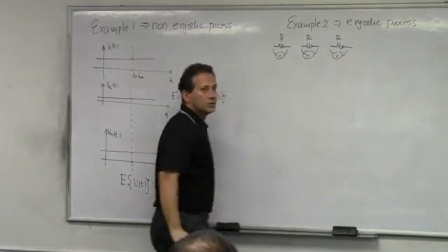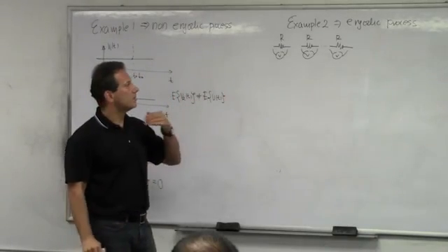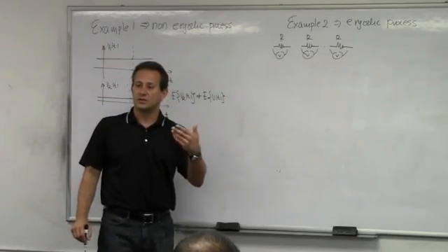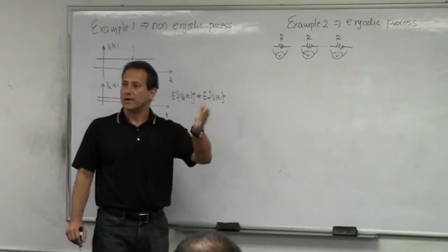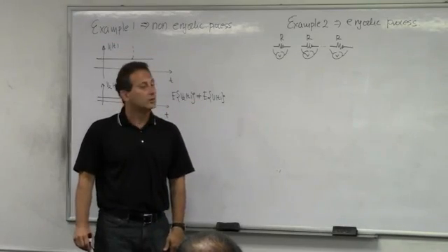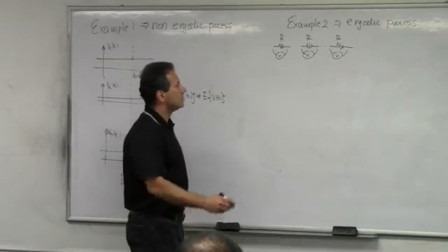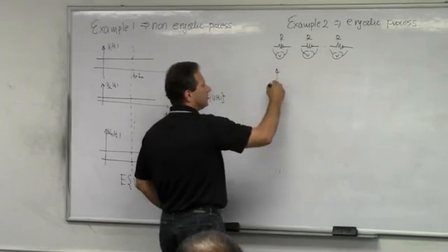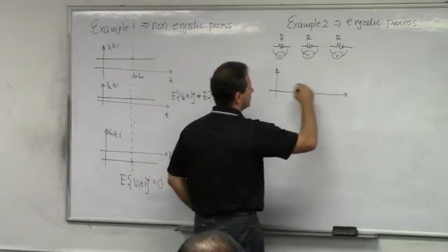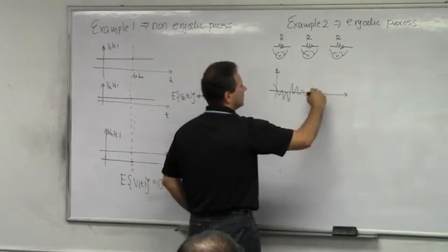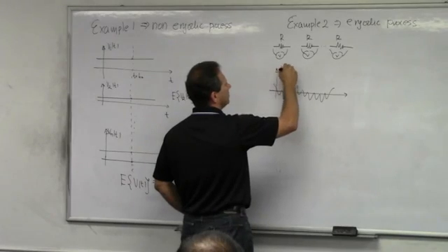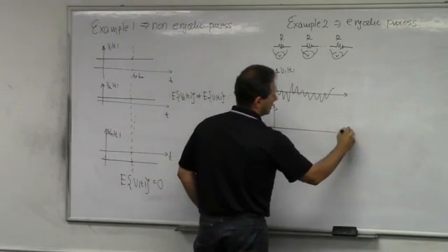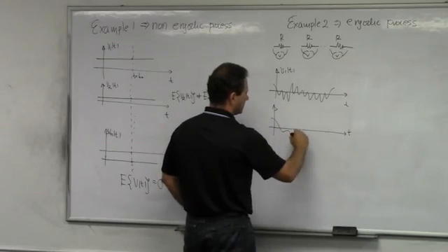And I'm measuring the voltage that is happening across these resistors. Since the resistors are not at a zero temperature, there will be random motion of the electrons going through them. And as a result, at the ports here, there will be some difference in the potential. There will be some voltage. And that would look somewhat like this for the first resistor. So this would be V1 of t. It will look somewhat like this for the second resistor.